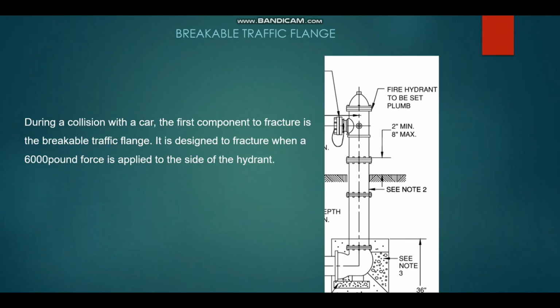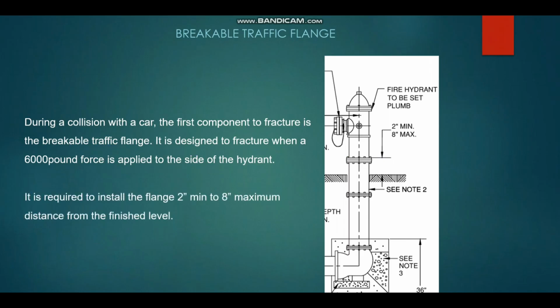And coming to the second important point, the installation point, it is required to install the flange 2-inch minimum to 8-inch maximum distance from the finish level. So normally if you consider this is the finish level of the road or the paved area, paved block, whatever it is, from here minimum 2-inch should be there and maximum 8-inch should be there. So this point we must follow when we go for the installation.